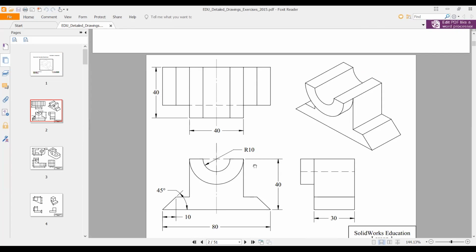That bulge that comes out, I will make it later. But what I'm seeing from the front view is exactly what I want to draw now. Everything in front view, I will just draw it out. Then I will extrude it by 30, then remove from there. Look at the side view, you see the 30. And the external that comes out small is actually 10.